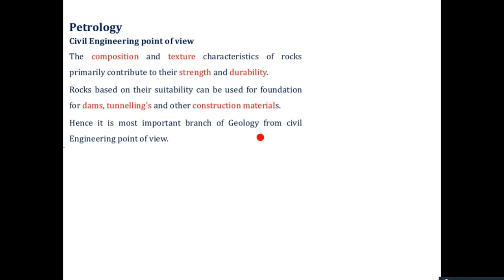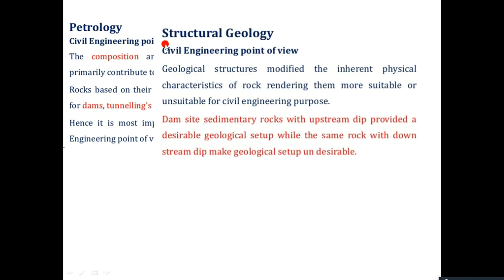So while studying engineering geology, you need to know what petrology is, because you have to know the composition, texture, strength, durability of the foundation rock on which the engineering structures are going to be built. You need to know structural geology. Why? Because if a fault is present or a fold is present, or the faults are in such a way that the stress is not able to distribute equally, that may cause rupture during an earthquake or any other such condition, or the rocks are fissile, or various other reasons, like if there is a stress zone or a gap zone, or if there are shear zones.